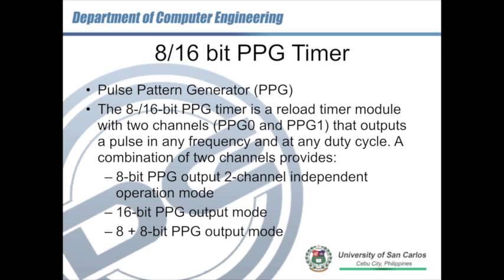Basically, the PPG timer is also able to modulate a pulse. So when we say modulate, we can change the duty cycle beyond 50% or less than 50%.